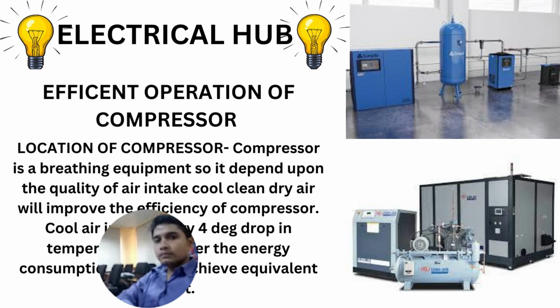Here we are going to discuss the efficient operation of a compressor. How we can use the compressor efficiently. First is the location of the compressor. Compressor is breathing equipment, so it depends upon the quality of the air intake. If the air is cool, clean and dry, it will improve the efficiency of the compressor. Every 4 degrees centigrade drop in the air temperature will lower the power consumption by 1%.